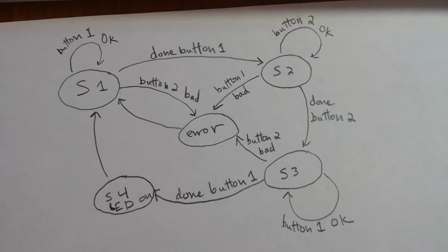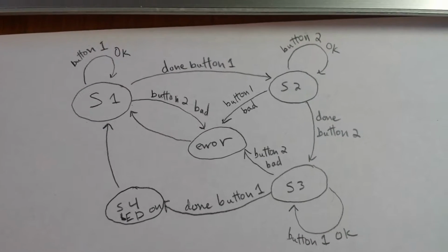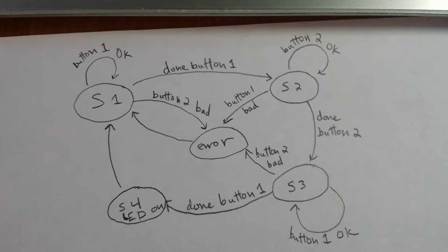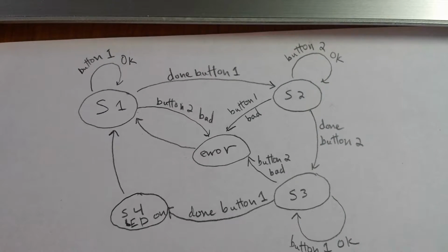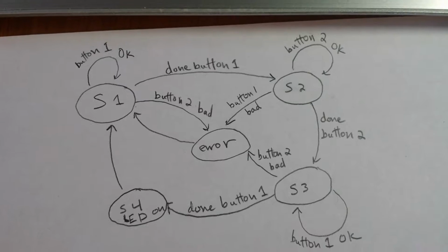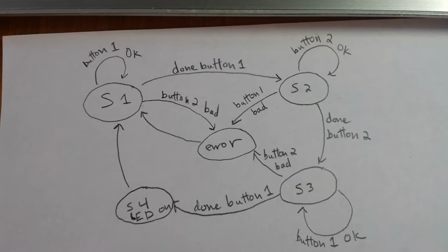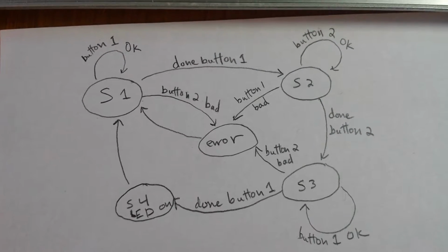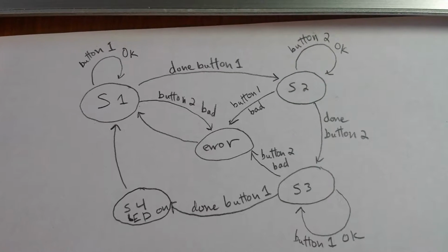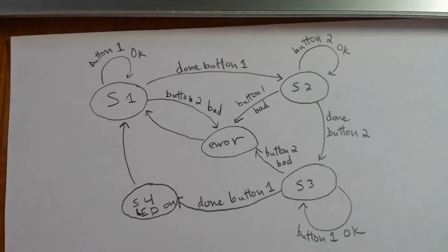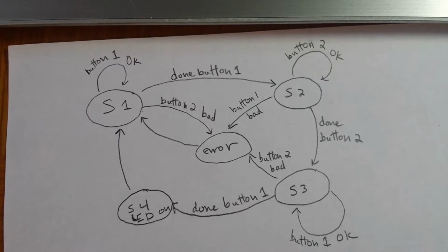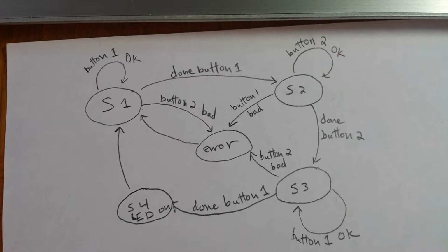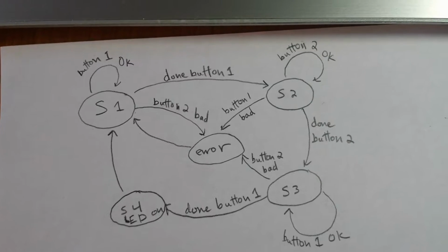captures the states of the code entry, in which each time a button is pressed, possibly for a repeated number of times, will represent one state of the code entry. And if you're in the midst of one state, you press the wrong button, which in this case is the other button, then the state changes to an error state, which flashes a message and reinitializes the state to the